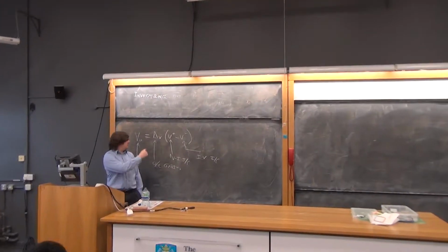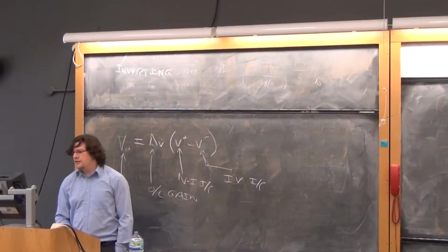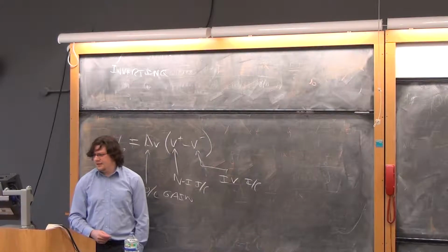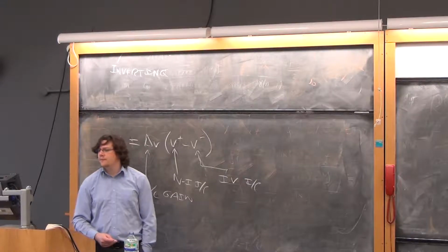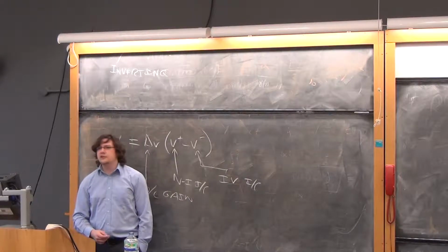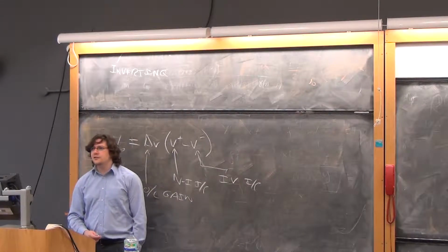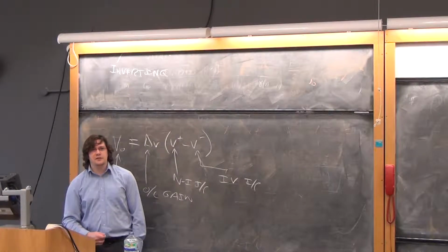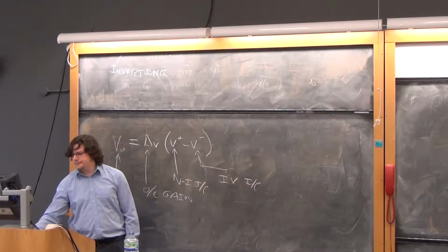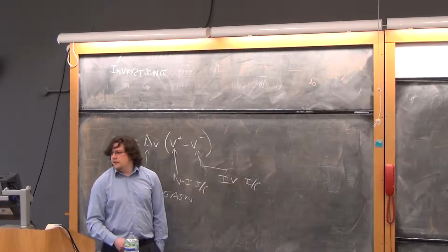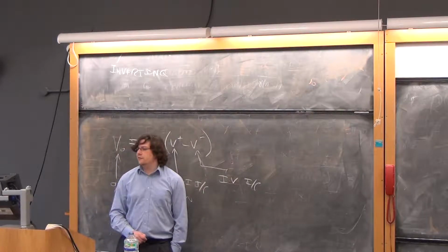So it's a mark for the equation and a mark for the labels. And then we get on to the real questions. Identify the op-amp circuit in figure 6A. So this is 6 part B part I. Which is it? Inverting. It is inverting. So you get a mark for knowing that it's inverting. Then the next bit says find an expression for V out over V in, assuming AV is infinite.